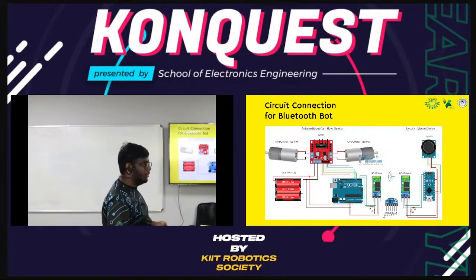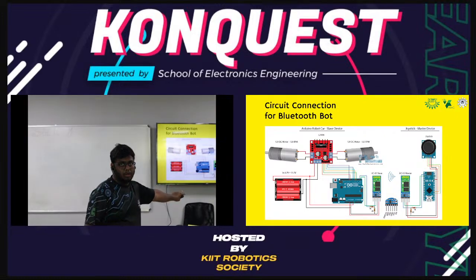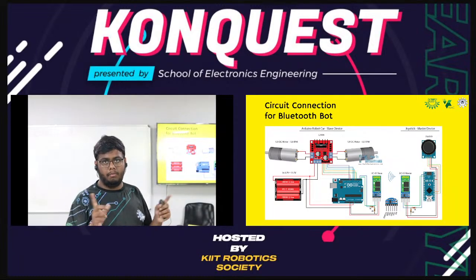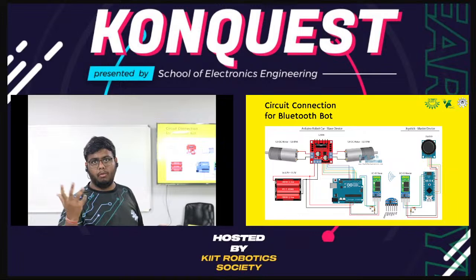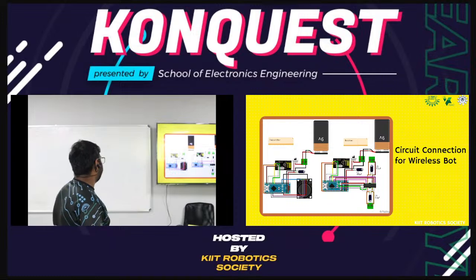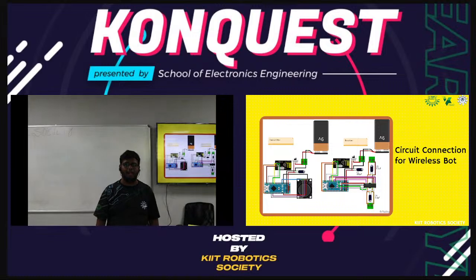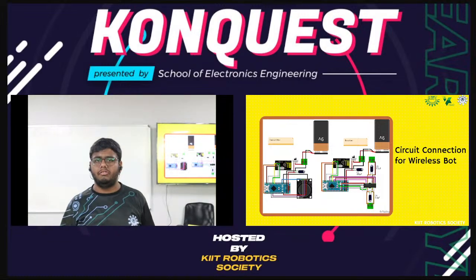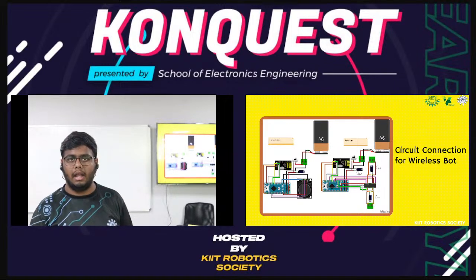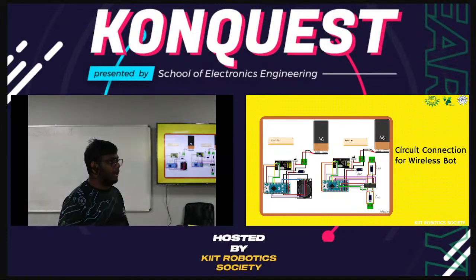But what's the difference from the Bluetooth control board? There are two Bluetooth modules. The HC05 is a Bluetooth module which you have to pair with each other to transfer data and communicate. But in this wireless board, we are using the NRF24L01. It's a wireless chip, and it's easily available in the market. You can get it at any robotics store.